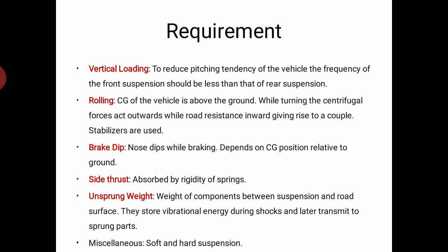Brake dip: the nose dips while braking. While braking, what happens? That is called brake dip. It depends upon the center of gravity position relative to the ground. Side thrust is absorbed by the rigidity of the springs. Unsprung weight is the weight of the components between suspension and road surface. They store vibrational energy during shocks and later transmit it to the sprung parts. Miscellaneous: soft and hard suspension. These are the requirements of the suspension system.